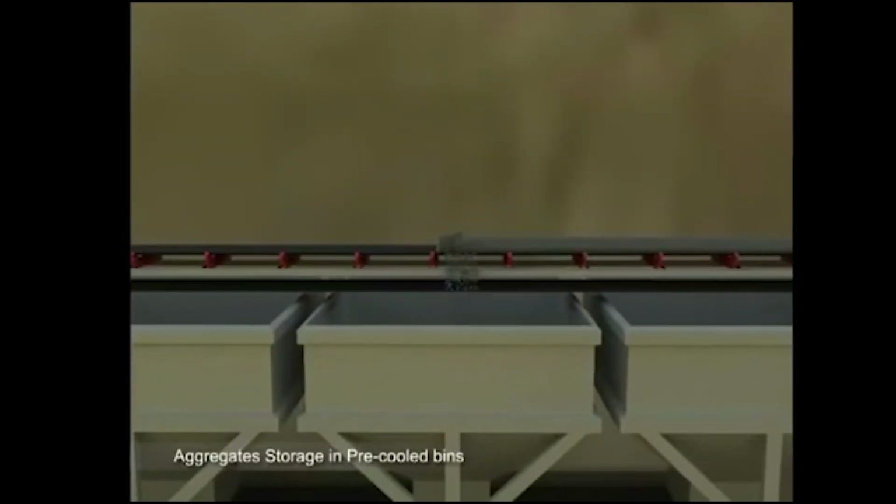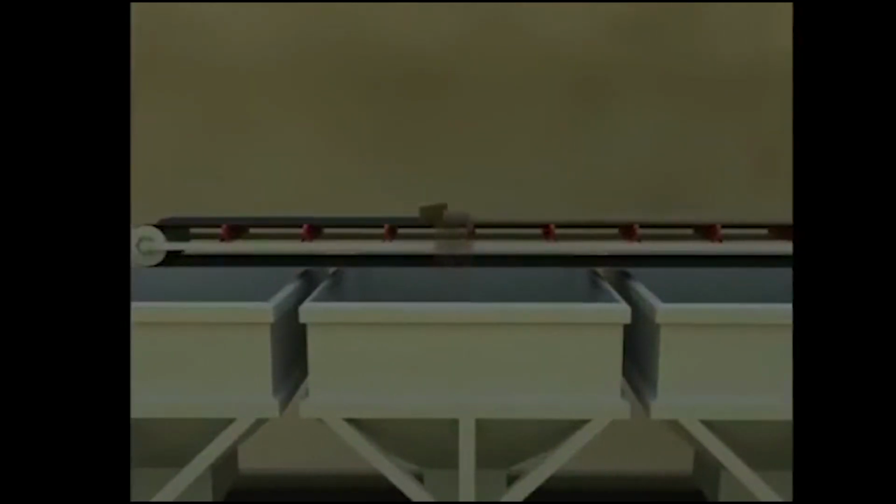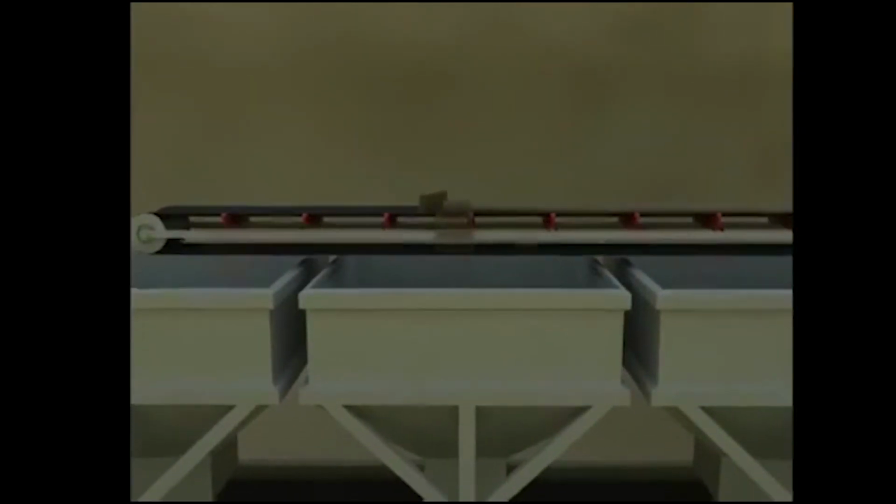Aggregates thus cooled are then carried via a closed conveyor and stored in pre-cooled storage bins. A strike plate mechanism installed over the conveyor directs the aggregates to fall in appropriate storage bins. Aggregates from pre-cooled storage bins are now carried via a closed conveyor to the batching plant weighing mechanism and further for mixing.